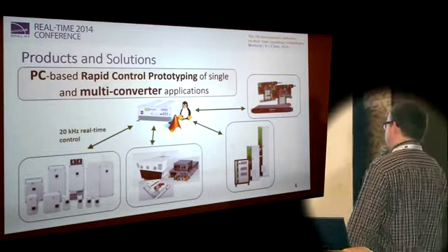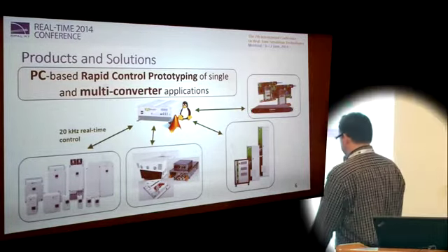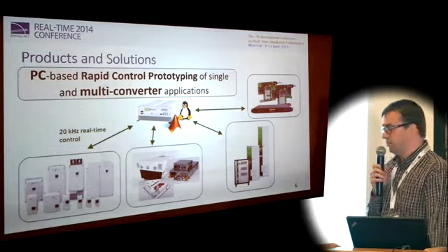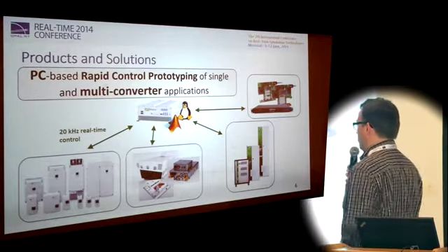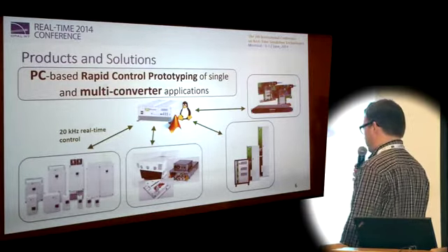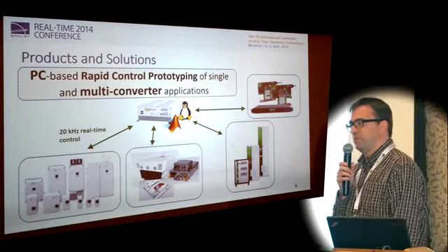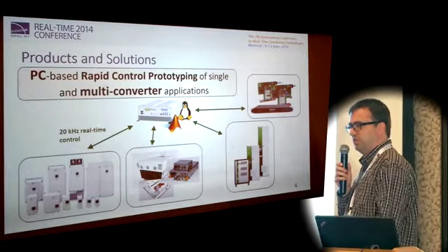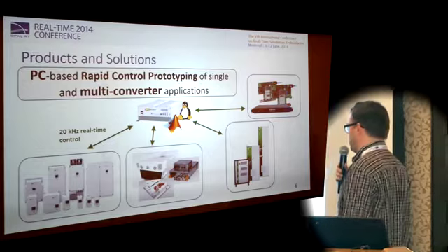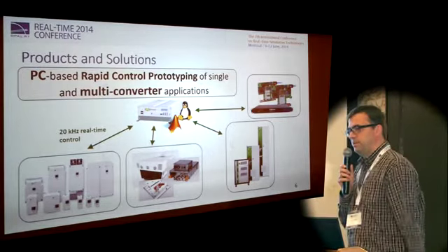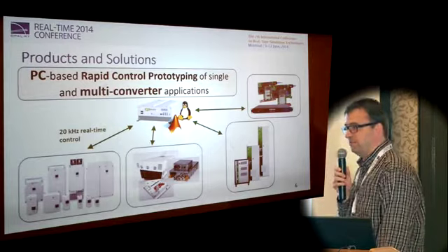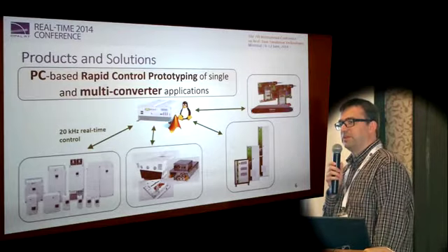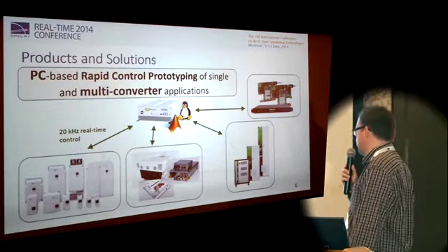Now the power amplifiers, the one you see here and the one we are going to demonstrate, are a kind of special case. It started off by us using our own power stacks, the power stacks that you see on the left of the screen, and we integrated them with a bunch of magnetics, switches, and capacitors to make everything you need to generate currents and voltages, to create current and voltage sources. Initially, we provided them as completely open hardware platforms, which they still are. So if you buy one, in principle you can entirely reprogram it down to PWM level.